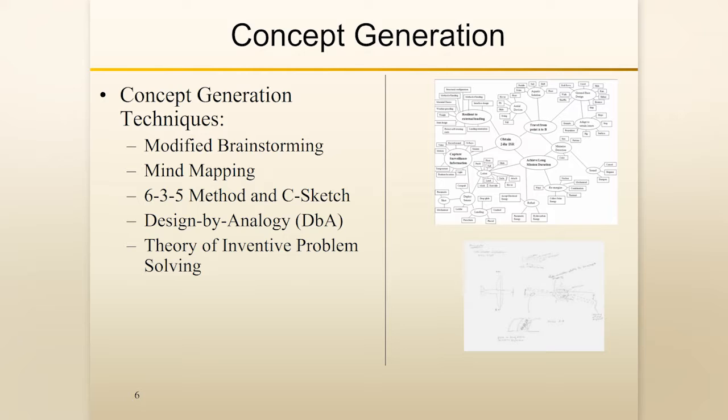Most design problems, especially mechanical design problems, are very coupled in terms of the relationships among design variables and performance metrics, and a lot of times performance metrics are in conflict with each other. TRIZ, or TIPS, is a technique focused on breaking through those conflicts.